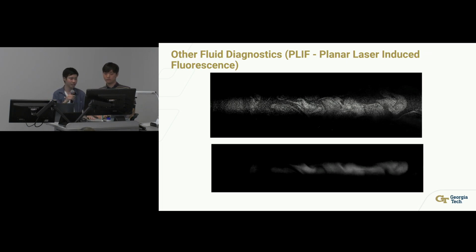So what is going on in this above image is a photo of PIV in action, in which we can see the different particles of the fluids and better visualize the mixing of the two fluids through those particles. Across an entire experiment, we would have multiple photos of this, as he told me, about 2 or 3 frames per second. From that, a camera or a program can analyze each and every particle and articulate the velocity field.